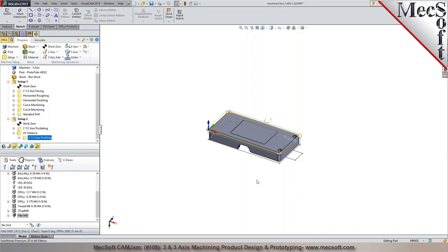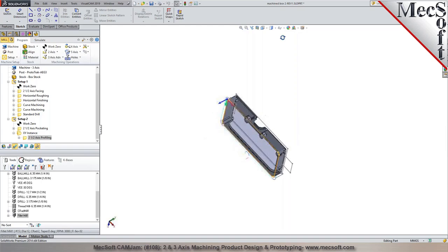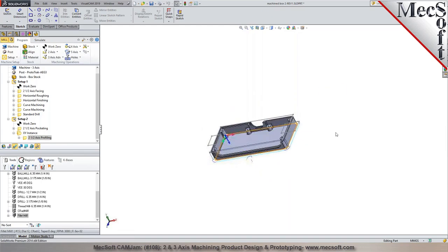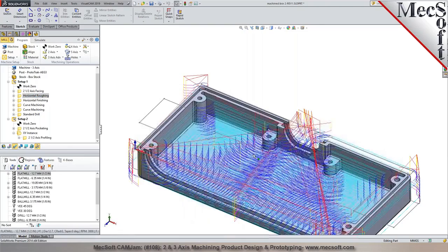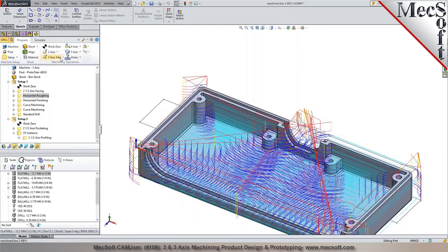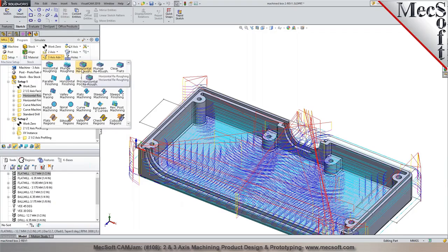So also the Pro gives you the options to do advanced 3D machining operations. So for example here, we did the roughing toolpath. Once you're through with the roughing operation, you could go back and do a 3-axis re-roughing, which looks at the stock from the previous step, and you want to go back and rough in areas where a larger cutter could not get in. So the re-roughing comes included. You have advanced finishing methods. Like we look at screen curve machining, pencil tracing. All of the advanced 3D methods are in the Pro.